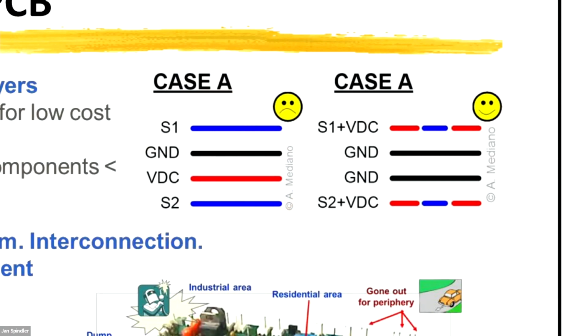This is not good. The good structure could be something like this. Remember that nothing is good or bad. In EMI, the best answer for any question is it depends. Nothing is the best option, no? In this way, you will not have mistakes. So remember, you have 4 layers. It's more important to have 2 ground planes and to use wide traces for the VCC lines for 3 volts or 1 volt than using a full plane for VCC, for power.